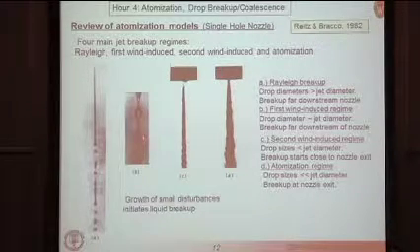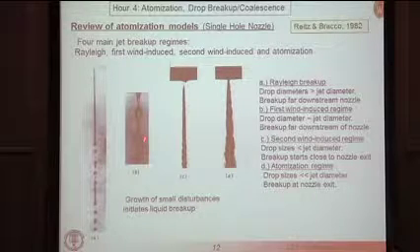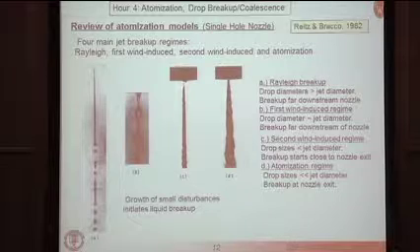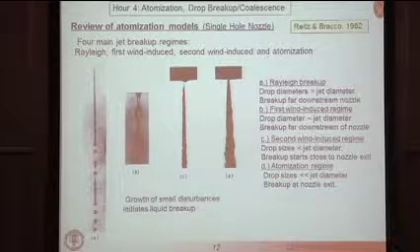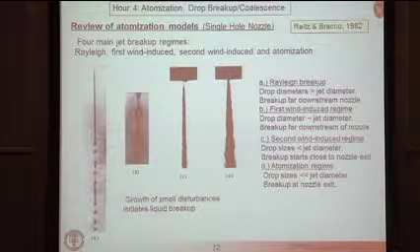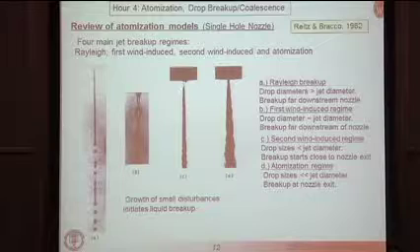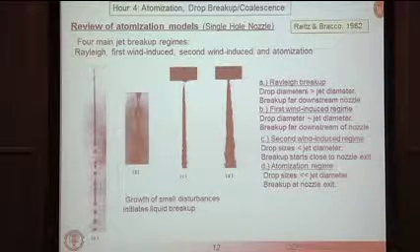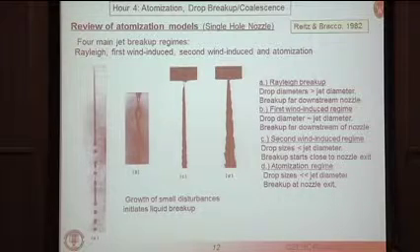As you further increase the relative velocity between the gas and the liquid, or you increase the gas density, the wavelength of these waves becomes much shorter, and eventually you see a little intact region here, and I'll show a blow up later, leading to short wavelength waves, which eventually break up the jet. And then finally, in the atomization regime, the breakup length here appears to go to 0, and you start to see what looks like breakup occurring right at the nozzle exit.